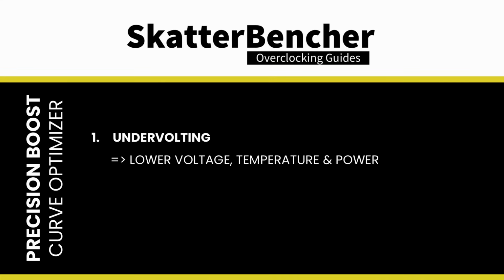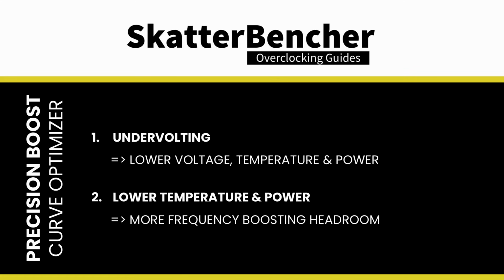The traditional approach to overclocking AMD Ryzen CPUs is to undervolt the CPU by applying a negative curve optimizer. That helps in 2 ways. First, undervolting lowers the operating voltage, temperature, and power consumption. Second, as a consequence, the Precision Boost 2 algorithm can leverage the additional headroom to boost to higher frequencies. So you tend to get lower temperatures and higher performance.